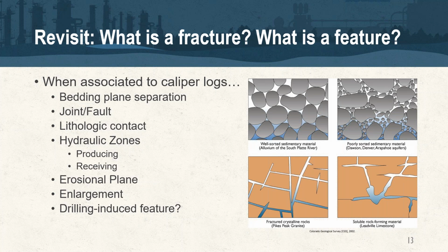Going back to the geophysics we discussed last week, we're looking for the areas where we believe, depending on the contaminant, where they may have propagated into those features, fractures, contact zones, secondary porosities. And again, doing that RDC process allows us to evaluate if it resides in that zone. So as we moved last week through the geophysics, the borehole geophysics portion of this is a very, very important component when we move to injection, because that's where we select our zones.